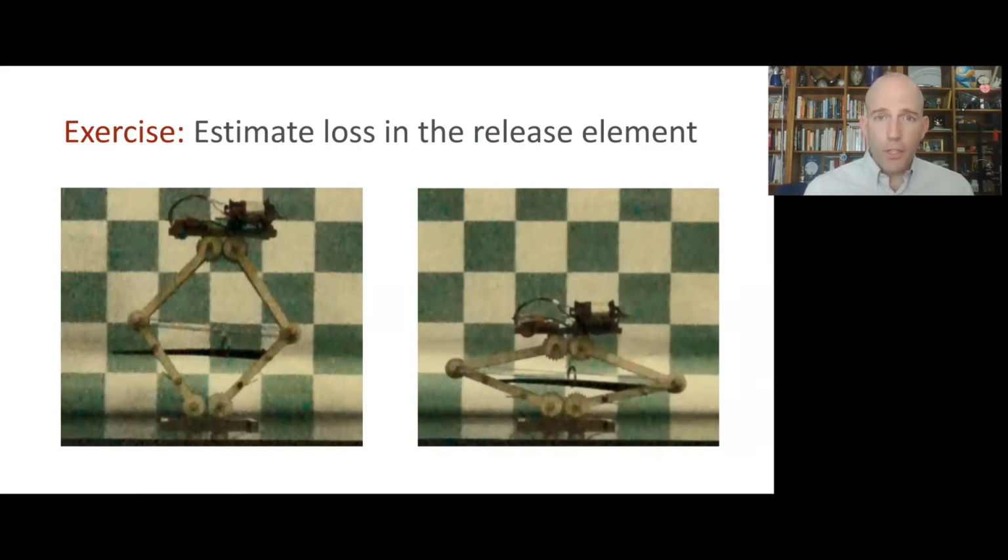All right, do you have a strategy? Hopefully that involved thinking about places where we could have sliding energy loss, energy loss due to sliding friction. And so we're going to want to have the friction force, which would be mu Fn, and some kind of displacement. And then to get the normal force, obviously we're going to want to do a free body diagram.